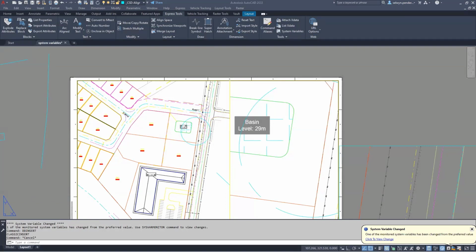Yeah. If you're working with files, or going out to Windows files and things like that, it's the FILEDIA system variable. If you're not getting certain AutoCAD dialog boxes, if they don't appear, it's CMDDIA. If that's set to 1, those dialog boxes will appear. Offhand, I cannot think, I've just gone blank with this one at the moment. But yeah, that's how we get those dialog boxes back, CMDDIA.